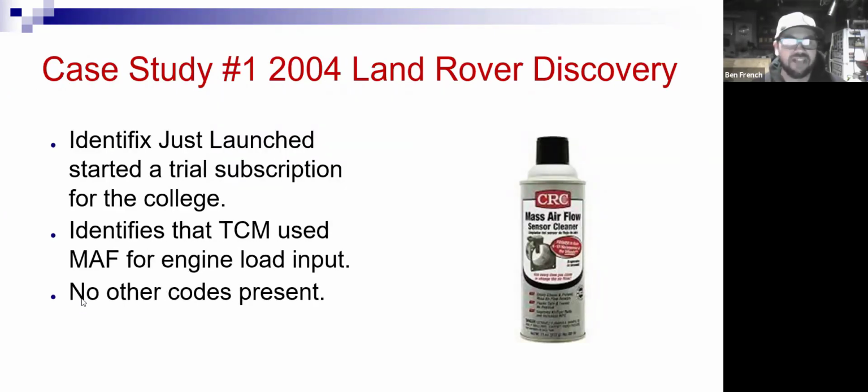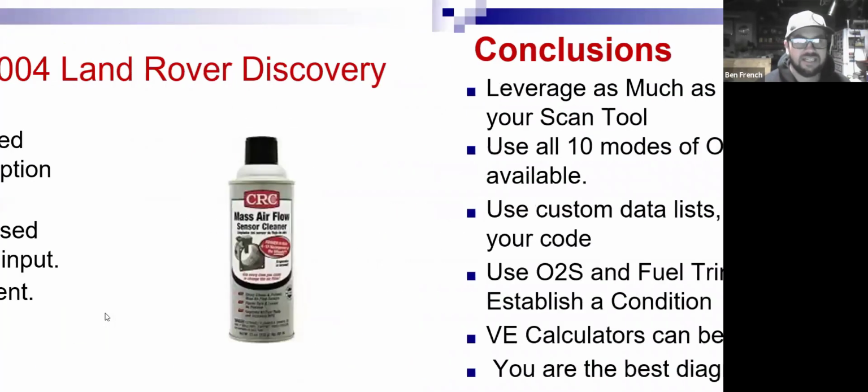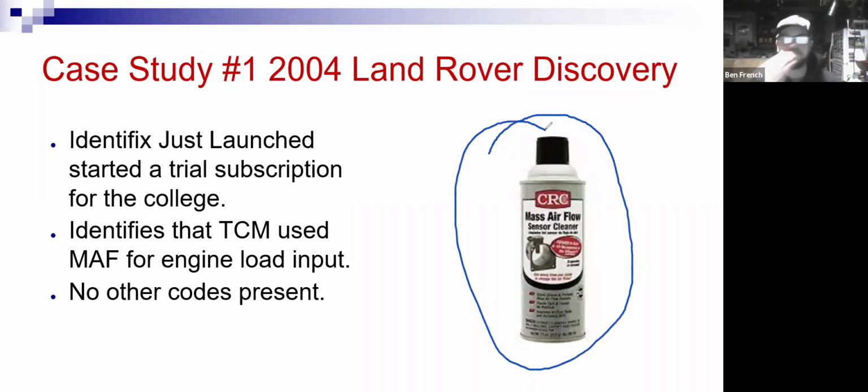So I identified the mass airflow sensor. What I did is I used some cleaner to clean the mass airflow sensor. Now, like I've told you guys, I'd always recommend using actual mass airflow sensor cleaner. If you put brake cleaner on there, it will destroy the sensor, okay?